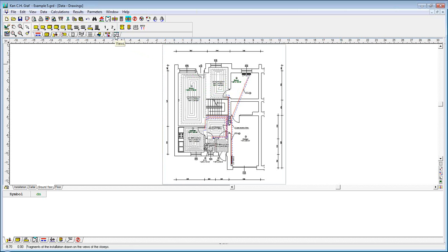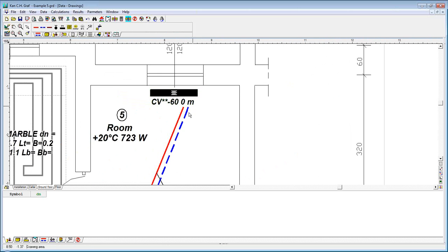You've got the specific table which is for plan views, and you've got here again the pipe, supply, return, one pipe, also valves. It's important that the program allows on the plan view to use only these elements from the start plan views and also from the graphics, because these are graphical elements without any meaning for the program. And for example, this is the radiator. The radiator in the room, in the plan view, looks like that because it's from the top.